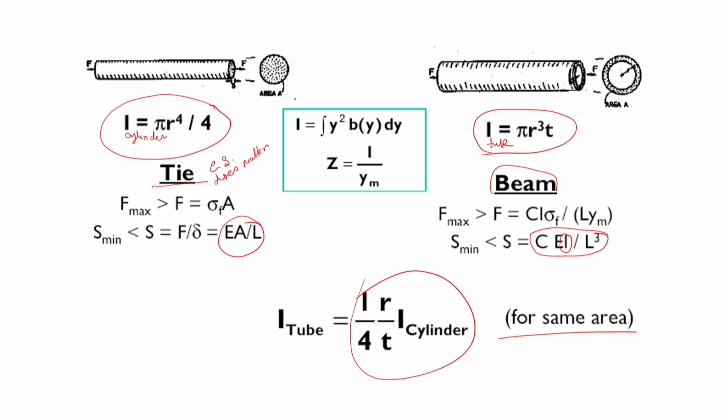And hence, for this type of a system, if I compare this stiffness with respect to a base stiffness, let us say for the same area, but either a solid circular or a solid square cross section, then we will be able to add this new factor which is called the shape factor.